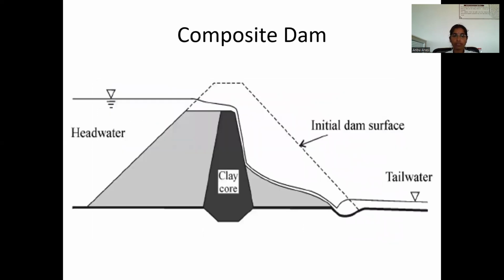Next, composite dam. Not only can different types of dam be built in the same valley, but the same dam can be of different types owing to the varying geological and topographical features on the dam site. Many buttress dams also join up with a gravity mass concrete dam at their flanks at the sides of the valley, and again at the center have a mass concrete gravity dam to form a suitable overflow or spillway.